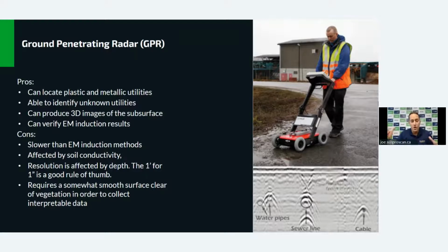You have to open up that manhole to get access to the lines leading to that manhole. Whereas with GPR, you can pick up utilities that might run directly through your site without actually coming up to the surface anywhere. So you can effectively image those utilities that otherwise you might miss or not be identified on records, for example.